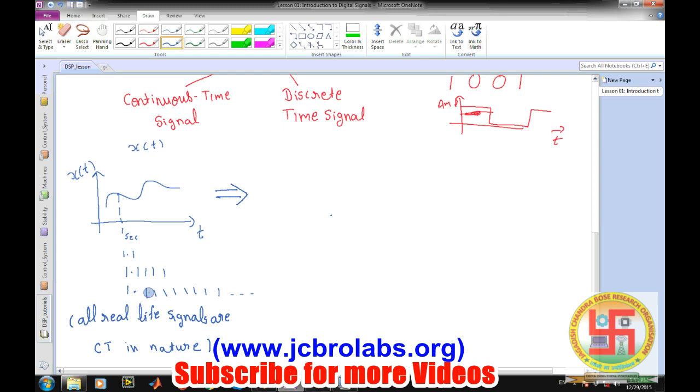So if we have some information at 1 millisecond, it is possible the information would be similar at 1.1 millisecond. That's why instead of storing all the information available in the continuous time signal, we discretize the time domain. Or another way to say it, we sample the time domain.